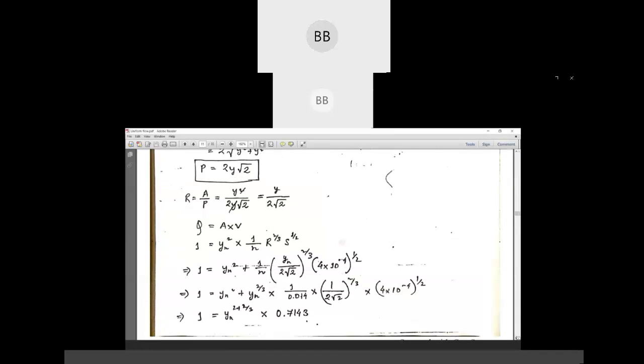Then we try to find out the wetted perimeter. If we consider the triangular channel, if this is the level of water, we are going to consider this side and this side. Like Pythagoras theorem, you find out one side and multiply it by 2, and you will get the wetted perimeter. Depth of flow is not known to us, so this is zy. If you do the Pythagoras theorem, you are finding root over zy whole square plus y square, and as we are considering the wetted perimeter, we multiply it by 2. Finally, you will get an expression like this: twice y root over 2.